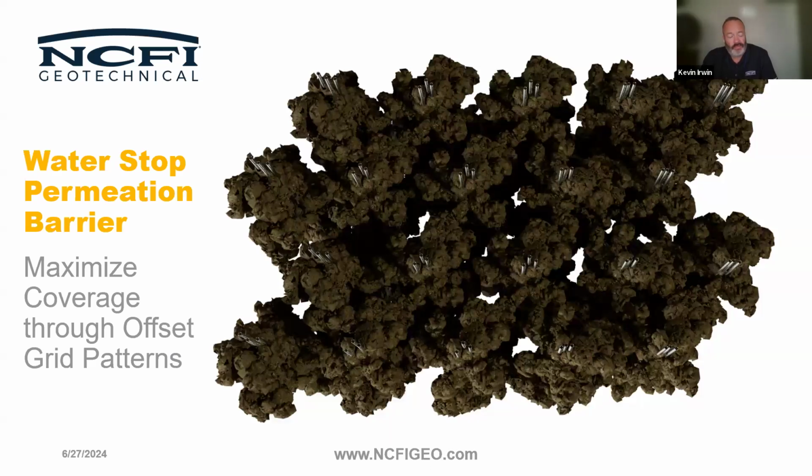There's many factors that go into deciding how far apart, but the main ones are, of course, the speed of the chemical, how fast it reacts, how long it stays liquid before it begins to react, and then how far it's going to travel. Somewhat the density of the chemical as well, and of course, what type of soil we're injecting into.